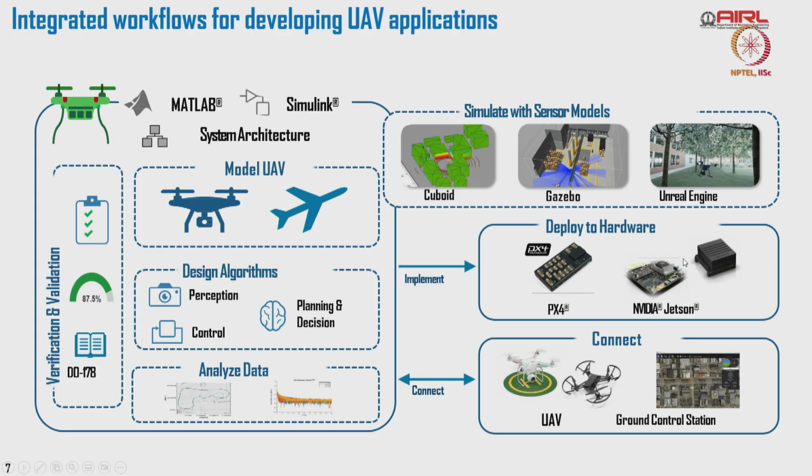When we deploy them, how fast is this algorithm going to run in this hardware to generate results? Let's say I am talking about 32 frames per second from a camera. But my algorithm, let's say I am implementing an AI module to detect an obstacle, I am not able to get more than 5 frames per second. Then how am I going to generate a trajectory and follow it? So these are the questions we really need to look at.